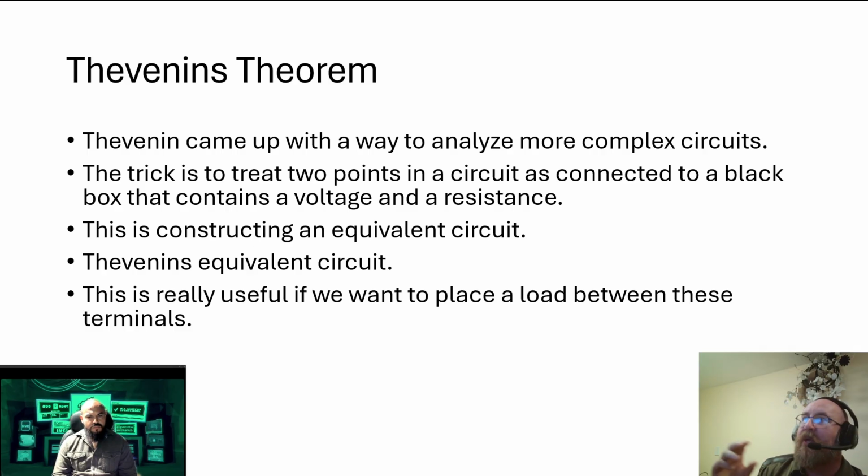Now, we can use circuit analysis with the full schematic, if we have that available to us, to derive what that equivalent circuit is and find out what our reading should be, right? Because if you take a measurement and you get a voltage, or you get a resistance, is that right? Is that what it should be? Well, you won't know unless you've done the circuit analysis to identify what the equivalent circuit actually would be, given the resistances on that circuit.